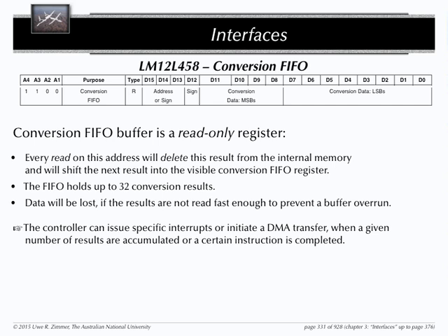You can set this at a certain fill level to give you an interrupt, so you're not accidentally overrunning. And this interrupt can then, for example, trigger a DMA transfer. Why would you do that? So you can be busy with all this stuff while the data is on. Yeah. You will in fact do this later.